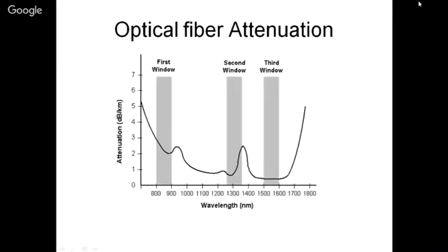At the same time, development was going on for 1300 nanometer, because you can see if the loss is 4 dB per kilometer in the case of 800 to 900 nanometer devices, the first generation, it would be even less than 1 dB. So you can go 10 times or 20 times more with a light source in this band.